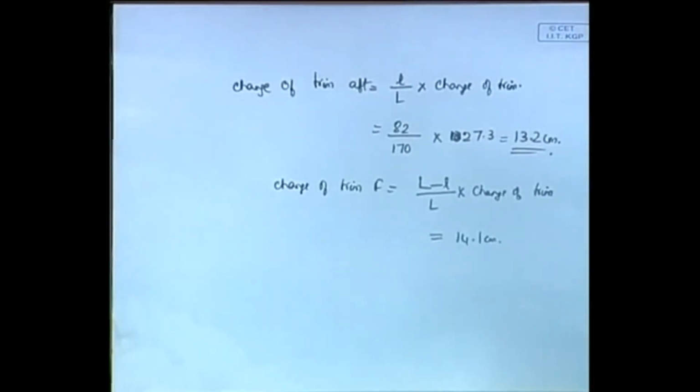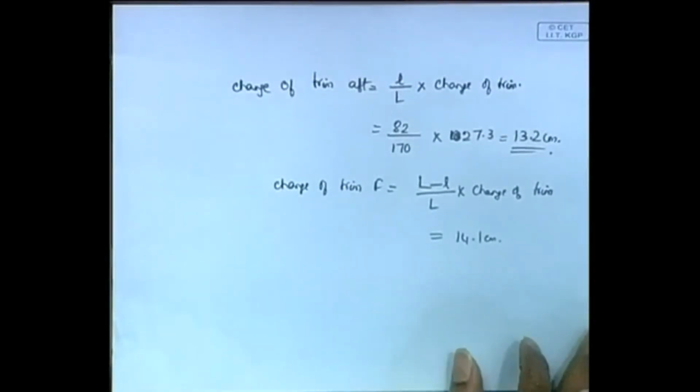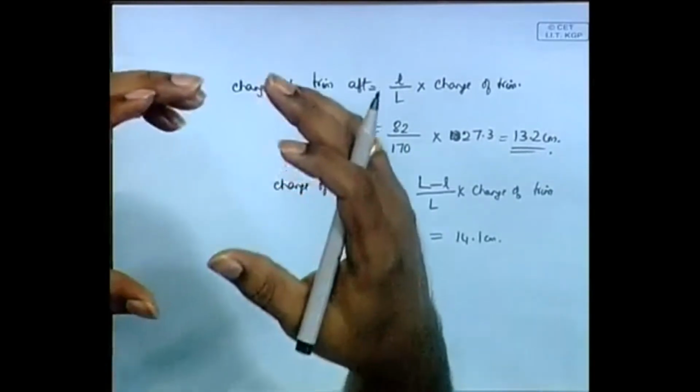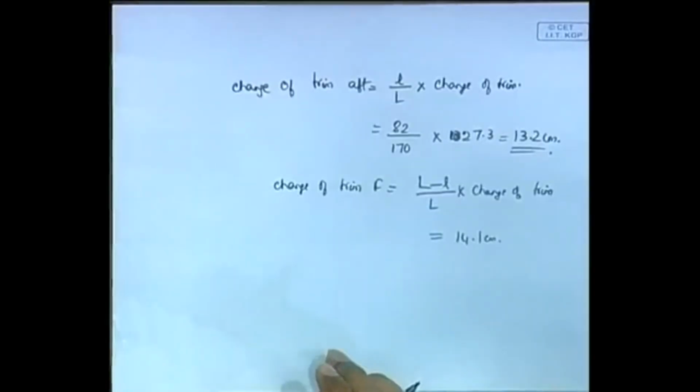This I have to check why it's so. It doesn't seem directly obvious. Okay, this I'll check and tell you. But according to them, they are saying that the ship trims by forward, not by aft. Even though the center of buoyancy has moved backward, in fact. Okay, let me check that. Is it a mistake here or is it correct? Anyway, I'll check that and tell you. Because accordingly, more volume is added at the aft.